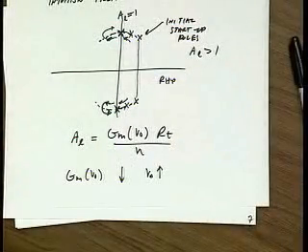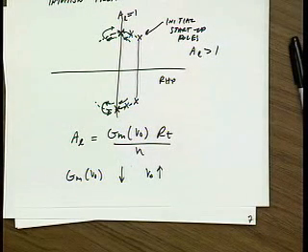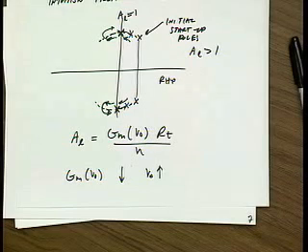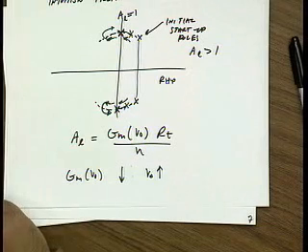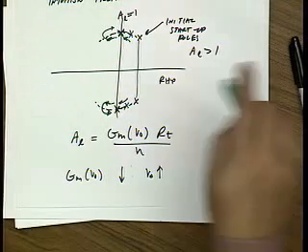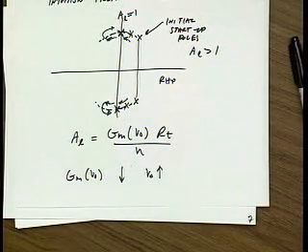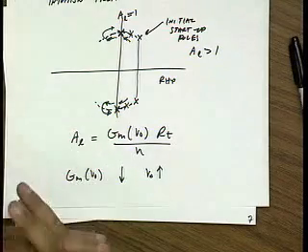Okay, Caleb? So can the setup you showed us ever be unstable? Can the oscillator be unstable? The setup you showed us, the inductor feedback. Yeah. In fact, somebody asked me last lecture, what happens if you have too much loop gain, for instance? You can get into a situation where the amplitude just keeps growing and growing, and the system just rails out, and then just dies on you. It's either supply rail. So you have to be careful when you design these systems that you simulate them over process, temperature, and make sure that your initial loop gain is a good choice that always leads to oscillation.